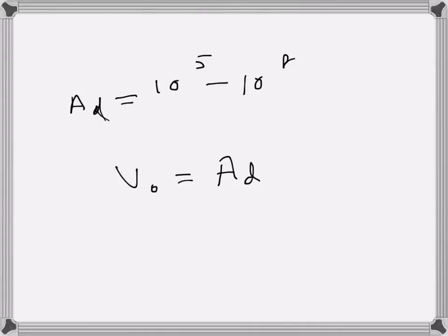Normally the gain is very high, 10 to the power 5 to 10 to the power 8, the voltage gain. That's the open loop voltage gain, but depending on the value of the voltage source, it's limited by the supply voltage. So the output voltage can be written like that. This is the gain here, and this is V2 minus V1. So if I draw the output voltage, it can be like that.